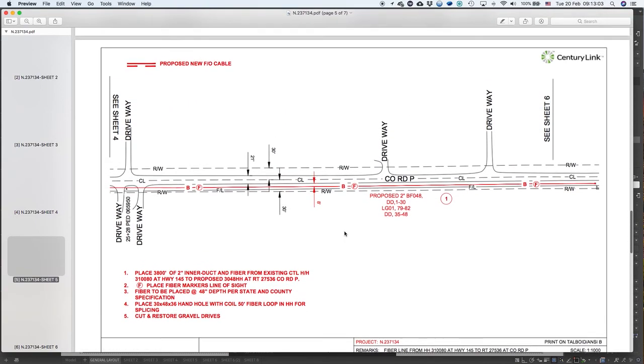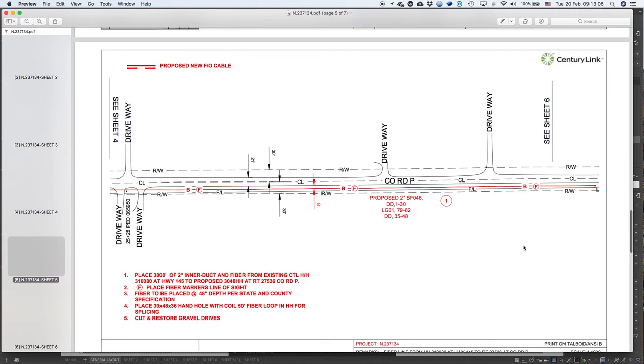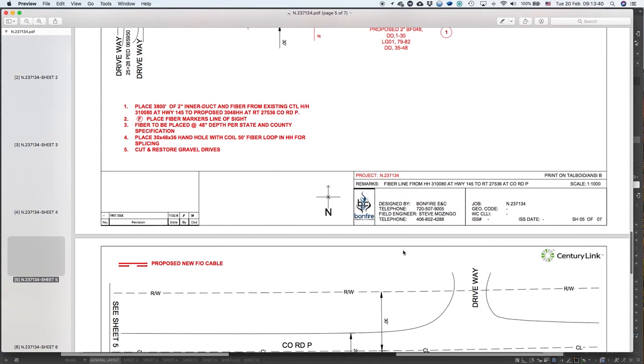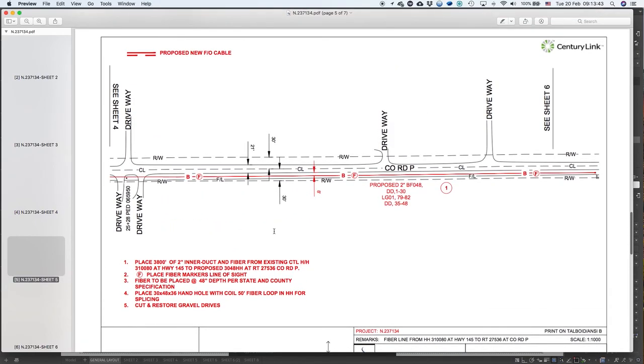So let's go to this page, make sure the sheet labels say 2 of 1 in the end and start page. All the features labeled, right of way labeled, center line labeled, fence line labeled, buried fiber labeled, 3 existing dimensions at minimum, one proposed dimension at minimum, label of the fiber, node 1, and all these nodes. Correct remarks, correct site IDs, correct scale, correct page number, correct engineer, and correct phone number. This is what you check on every page.